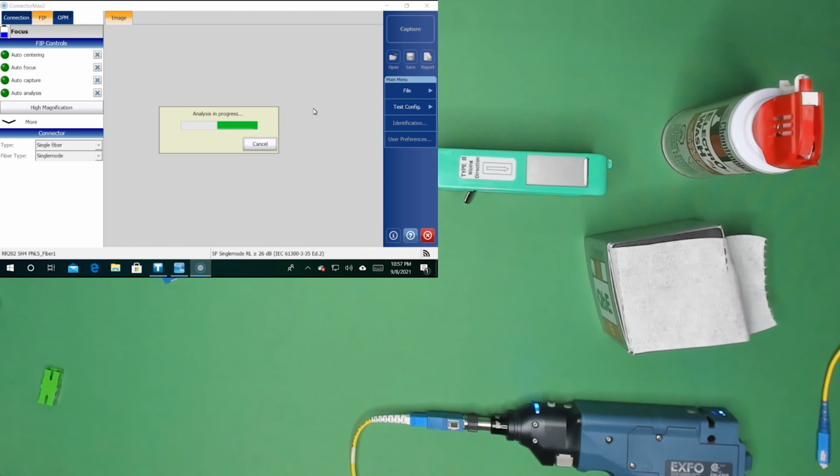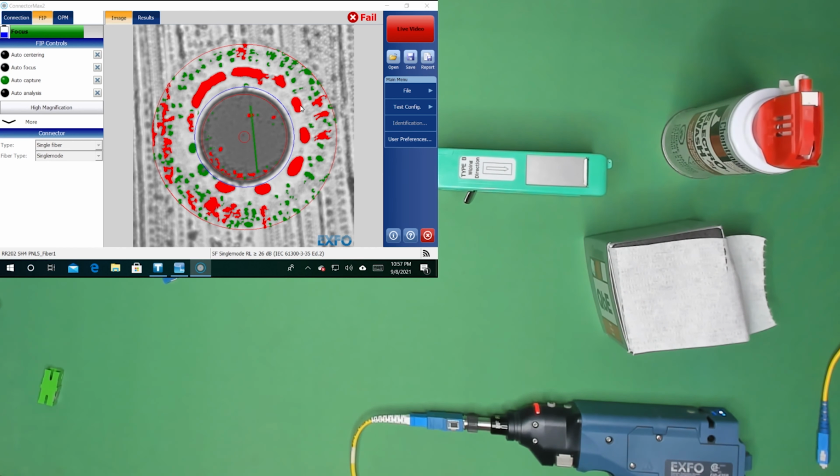And we're losing a little bit of resolution going across VNC here. But essentially, obviously, we have a bit of a train wreck here. If I double click on it, you can kind of see. Anytime you see this rounding, almost like this cratery effect of debris, how it pushes itself out, this is a contact zone. You can see how all the oils push themselves out to the end. This means that there's cross-contamination. It's been plugged in dirty.